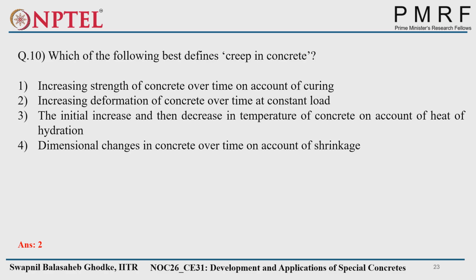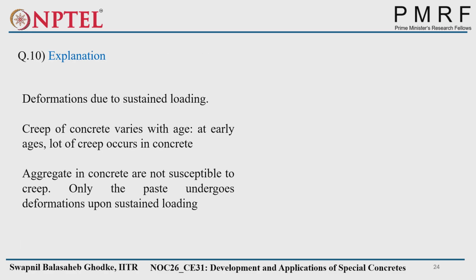Column is there, certain amount of deformation due to the creep or certain amount of load happens. So what will be responsible for that initial deformation? Coarse aggregate or paste content? Mortar. Yeah, paste or mortar, because coarse aggregates are very stiff and not responsible for the deformation at all.